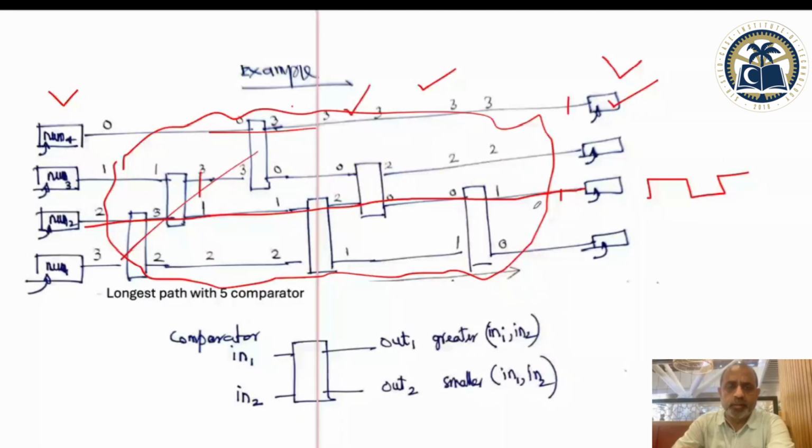Sometimes, while you are designing, you know that you are creating a very big combinational cloud, and it is never going to meet timing. So you have to think at that point, once you are designing the architecture, whether you should go for such an architecture where there is a big combinational cloud. If you really don't know where your registers are in the design, then it becomes a challenging problem to do the timing closure. Just looking into the Verilog code and figuring out where to insert registers and how to pipeline becomes very challenging.